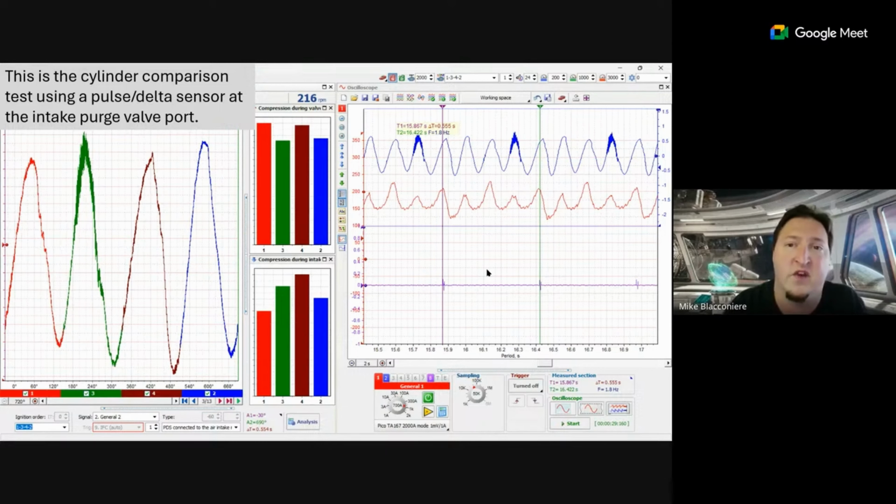And the reason for that is, sometimes you're going to run into a weird set of circumstances. It's not going to make it run very well. But then typically you have an obvious problem. So this test is nice when you're trying to pick out very little problems, like this intake valve leak here on cylinder number 3. This engine actually had a lot of different problems. The guy cooked it and drove it 20 miles with no coolant in it. But it was a good case study anyway.